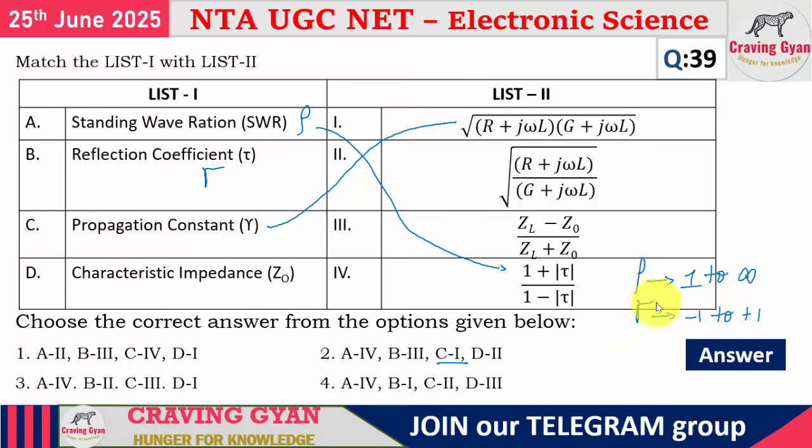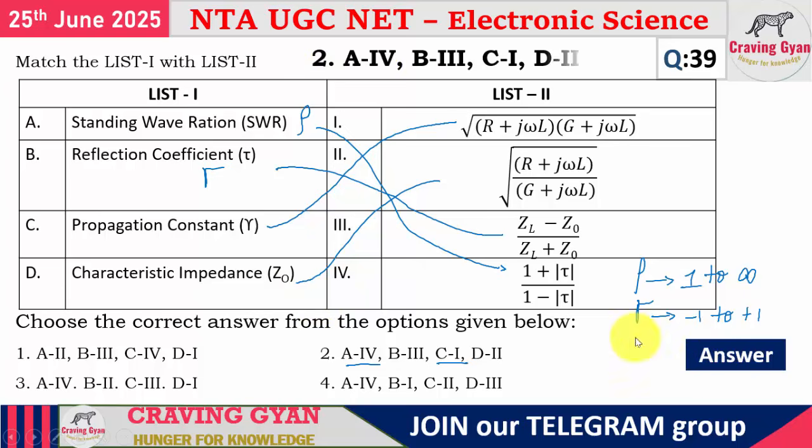Here they have given the reflection coefficient as tau. Now how we define the reflection coefficient gamma: gamma equals (ZL minus Z0) divided by (ZL plus Z0), and the characteristic impedance is given by this one. So the corresponding option that is going to follow is option 2. Option 2 is correct.